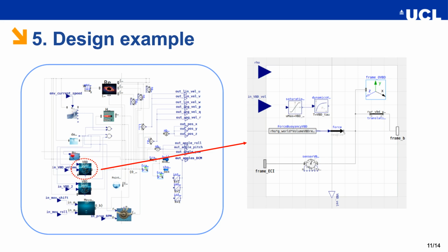In this hybrid glider, there are also two variable ballast devices which are used to generate additional buoyancy forces. The buoyancy force is again saturated to the physical limit associated to the volume of the actuator and implements the dynamics of such an actuator. The other blocks represent the physical connections to the different frames.